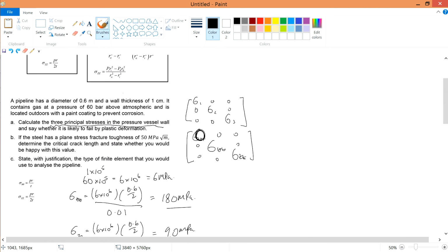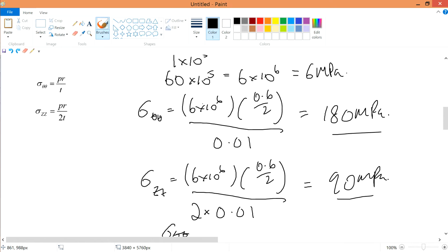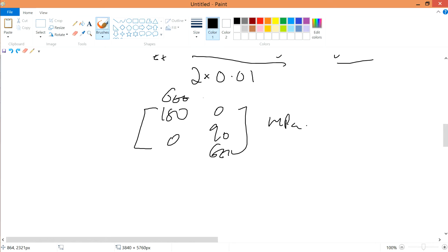Alright. Now, this is to get the principal stress. We have already shown you the principal stress that is over here. This is your principal stress, 180 and 90, where this is your sigma theta theta, and this is your sigma ZZ, or your longitudinal stress.